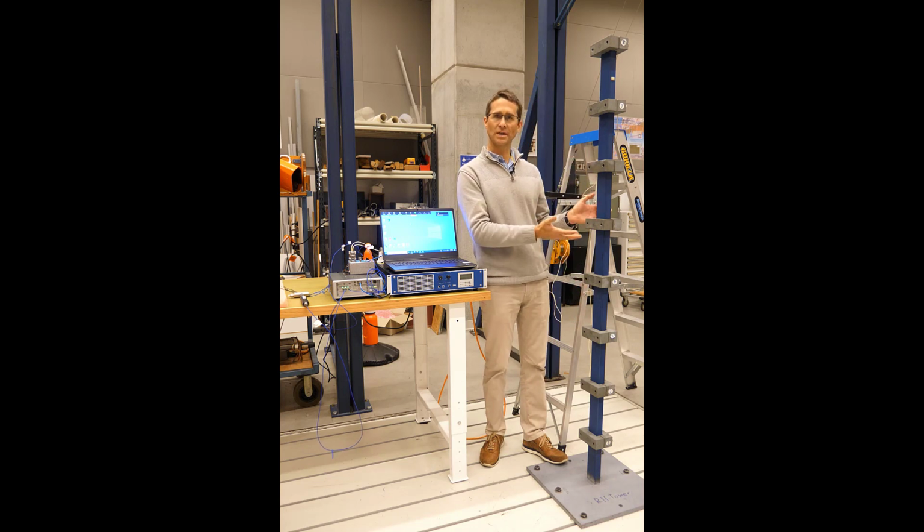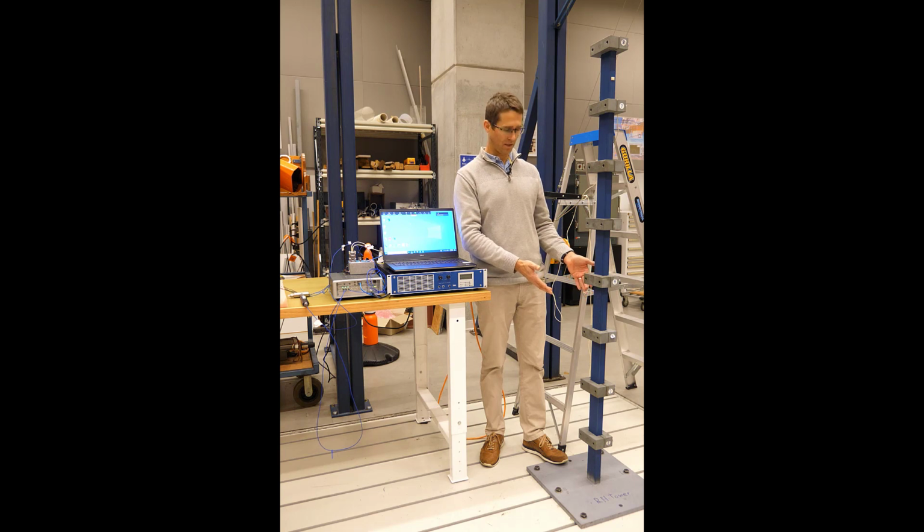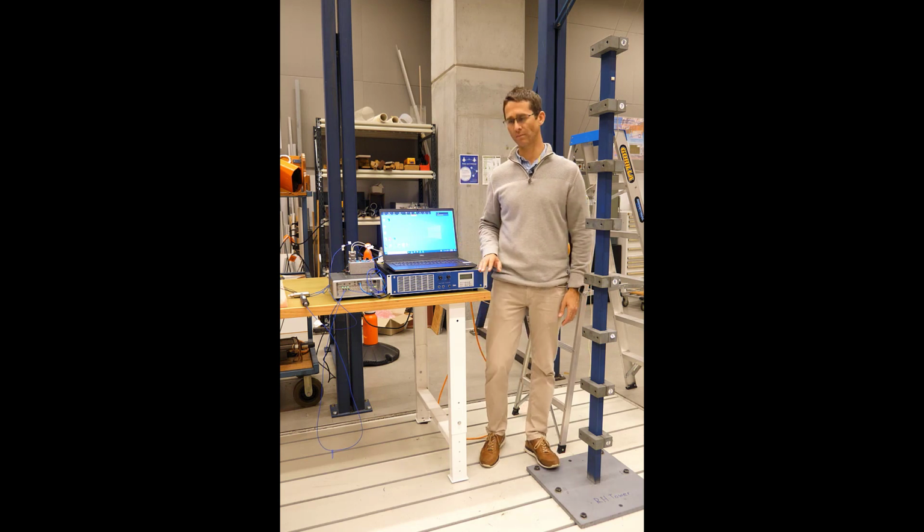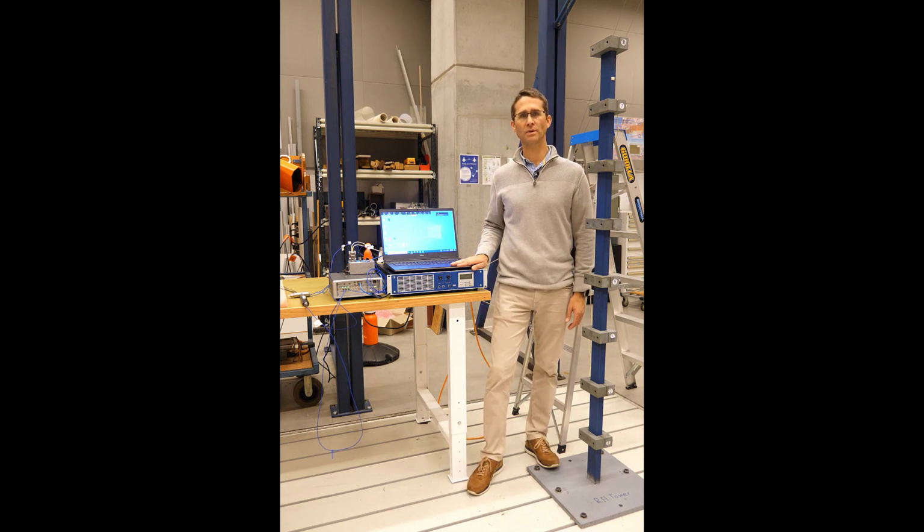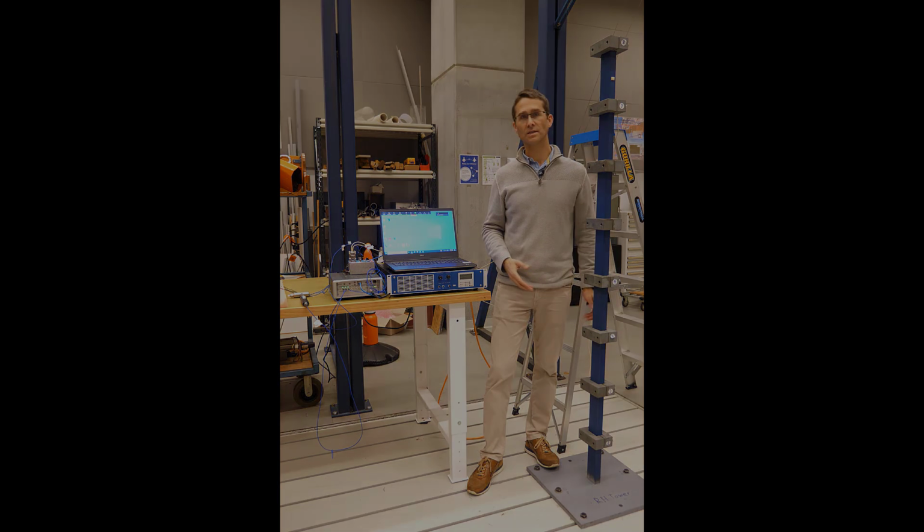We have the geometrical details and the material properties for this tower, so we can simultaneously undertake a simulation using, for example, SolidWorks simulation, and we can predict the natural frequencies and mode shapes of this kind of a structure and compare and contrast them with those that we can capture from experiments. This video will work through in a detailed way how to set up the acquisition system, how to validate this channel setup, how to build a geometry, how to collect the data sets.